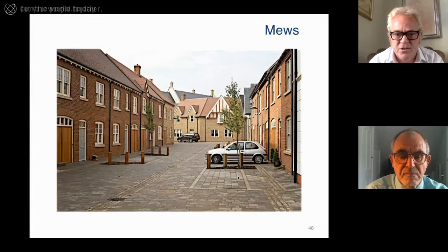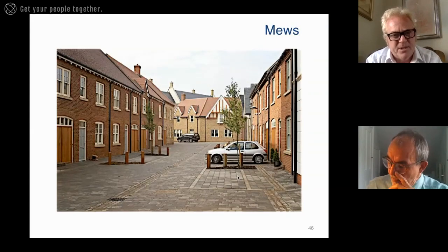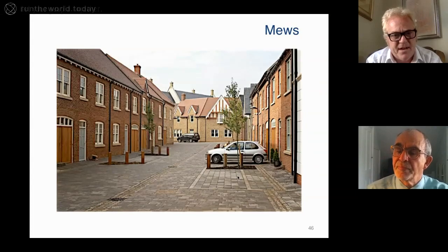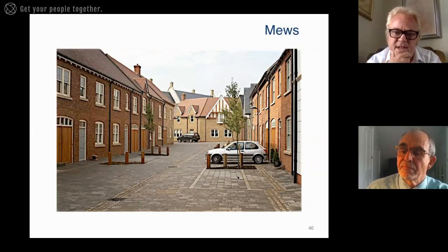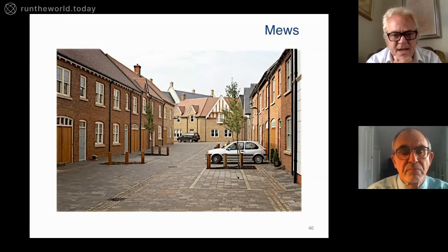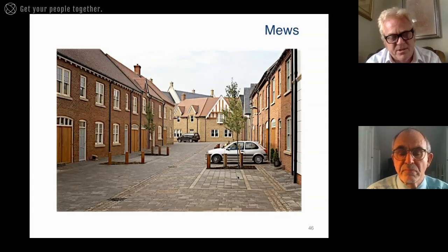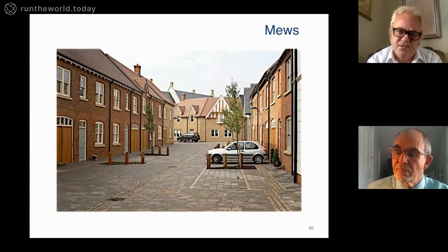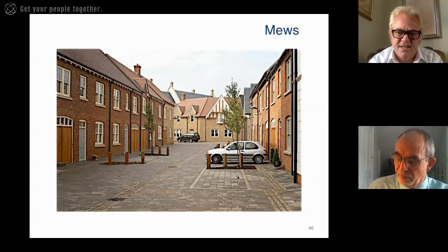That's one of the SUDS systems on the rural street. And then this is a more hard landscape mews. So what we learned from that was, in a way, to keep it simple. The danger is if you create too many character zones and the developer jumbles up the house types as if they've sort of sneezed on them, then it feels awful. I think if there's a formality or informality, or urban to rural, then it's much more successful because the whole thing's just much calmer and easier, and also easier to build. That mews is relatively easy to build and pretty successful.